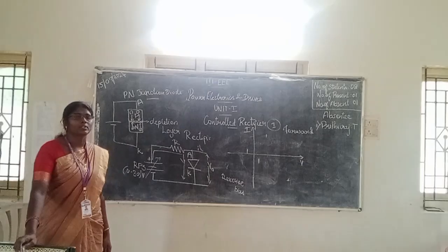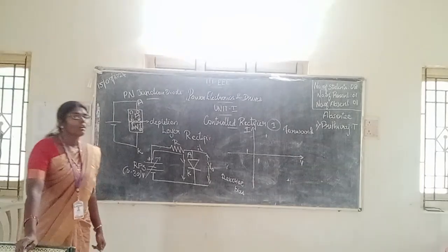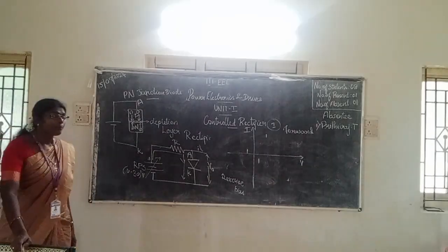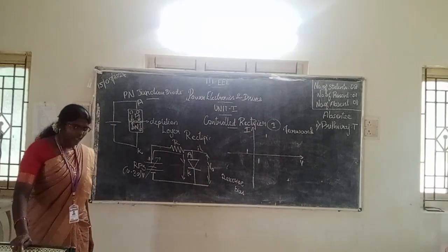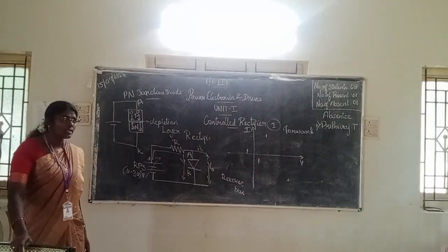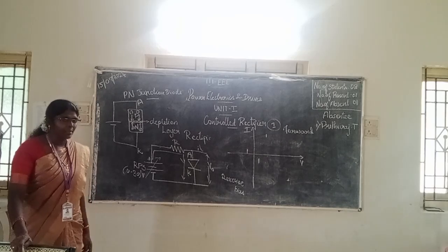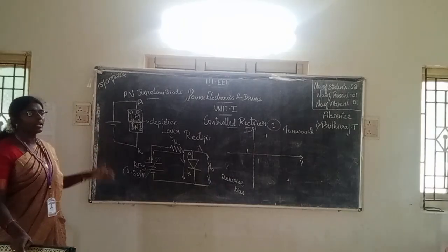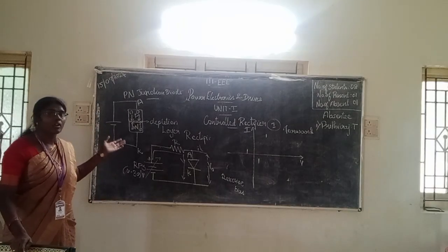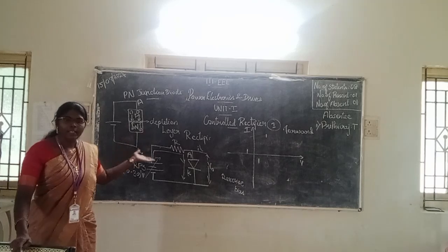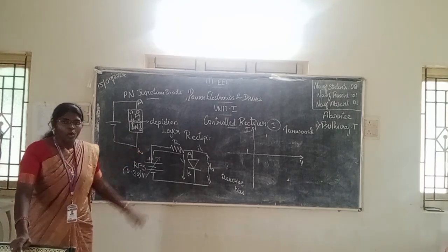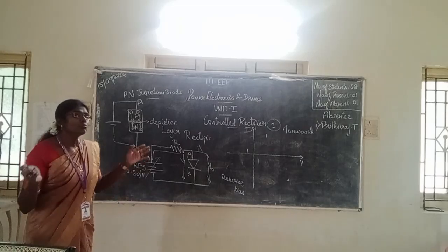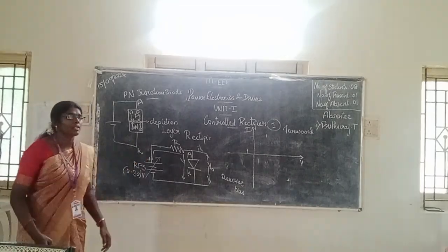That is why I write the operation. What you have to say: when the anode is connected to the positive terminal and the cathode is connected to the negative terminal, the holes from the p-type semiconductor and the electrons from the n-type semiconductor. Why is it electrons? Negative electrons are in the n-type semiconductor. In the p-type semiconductor it will be holes. Both will move towards the depletion region.